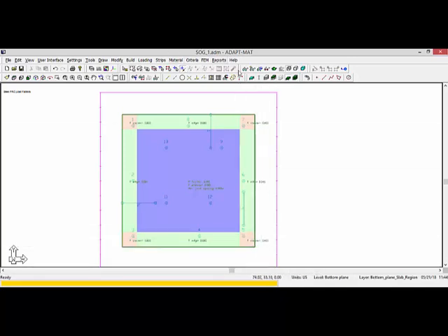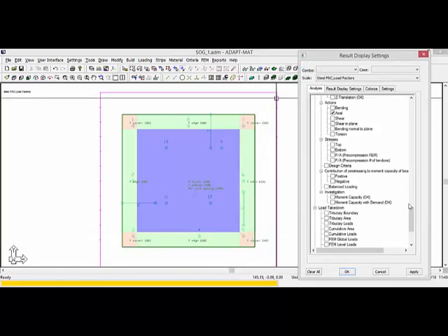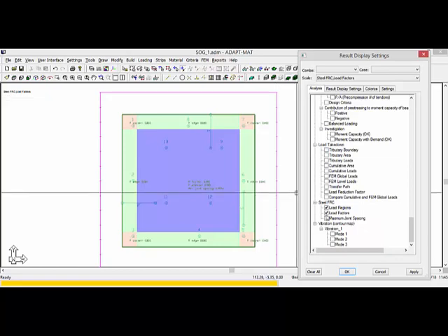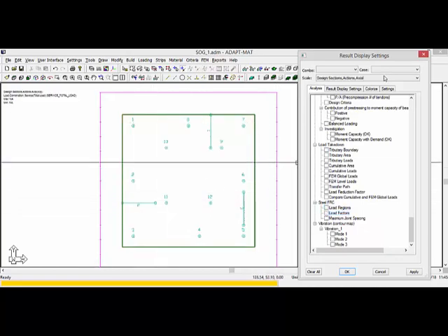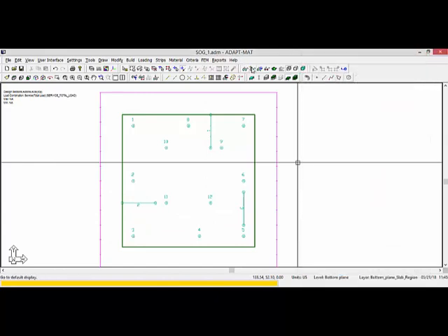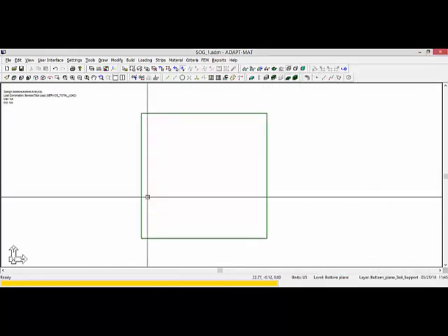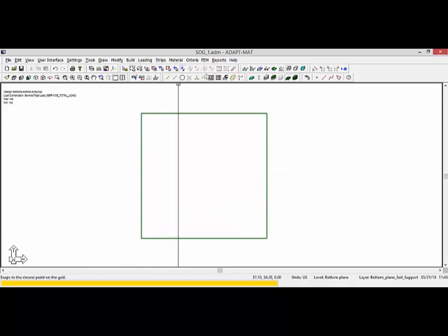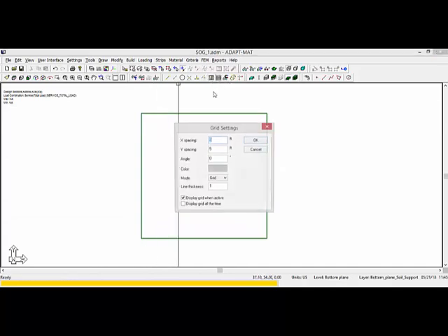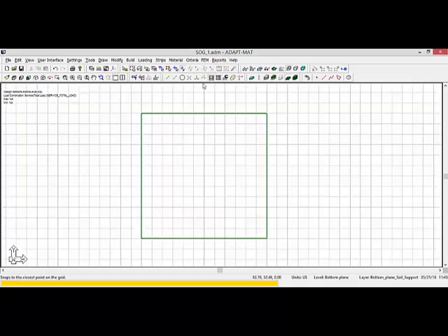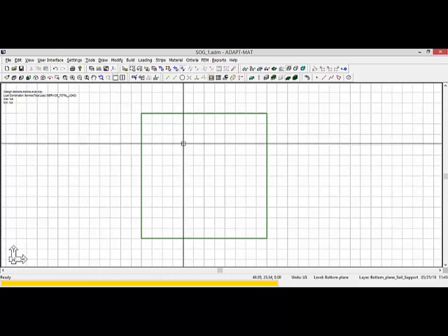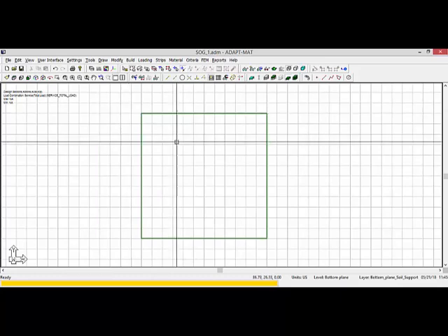We'll come back into the main model. I'm going to go back to the red eyeglasses, and I'll turn off these options here for the regions and the factors. I'm actually going to just default display the model and go back to just a single slab. And now I'm going to add support lines. So I'll turn my grids back on. My grids were at 5 feet, and I'm really just going to turn these 5-foot increments into uniform strips in either the X or the X and the Y directions.